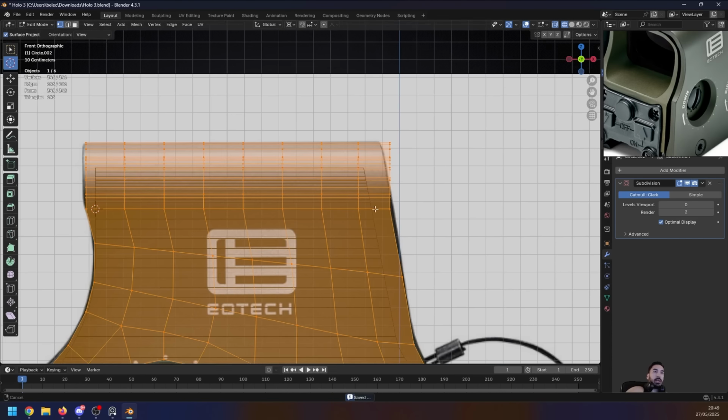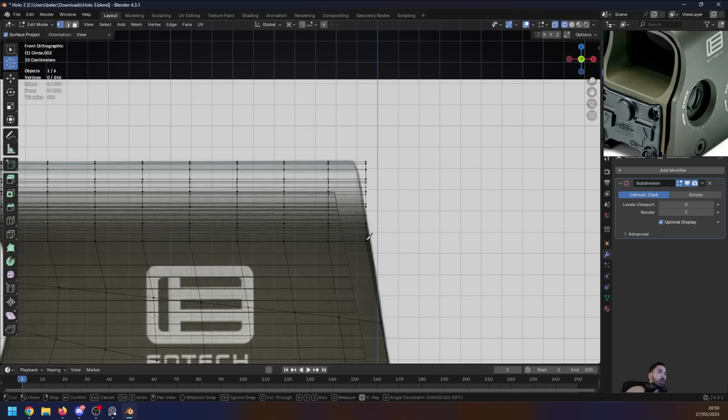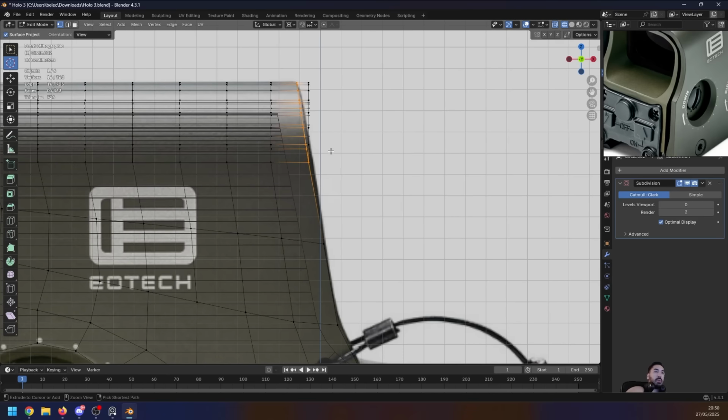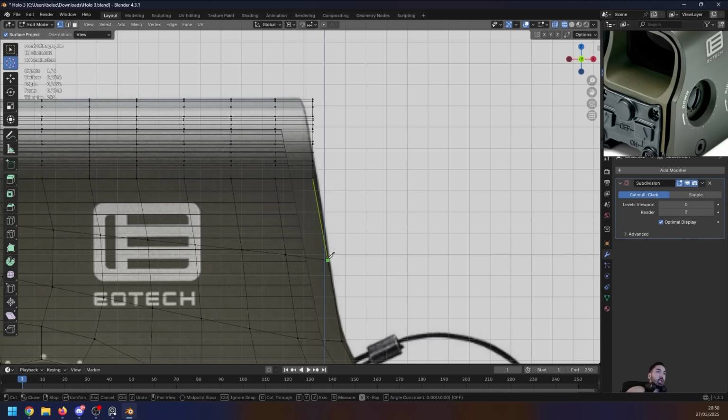We just have to take care of the shape, so let's just place a knife cut over here in the front. We're going to click here, press C to cut through, and then click up here. Maybe we want to be a little bit more precise, so I'm going to start the cut over here. I'm going to continue it through this vertex on the corner, and I'm going to make sure that this little square which you can see on the corner turns red. You can see that right now, and then press C to cut through and click right here, hit enter.